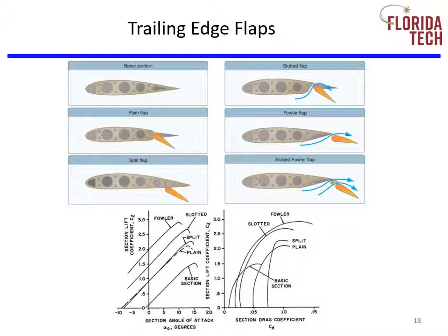The effectiveness of flap on wing configuration depends on many factors. One important factor is the amount of wing area affected by the flaps. Since a certain amount of wingspan is normally reserved for ailerons, the actual wing maximum lift properties will be less than that of the flap two-dimensional section. Recently, attempts, some more successful than others, have been made to increase total aircraft lift coefficient using full span flaps in conjunction with spoilers for roll control.